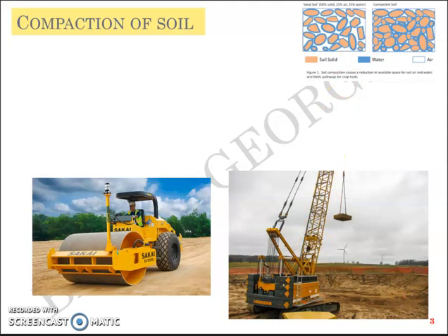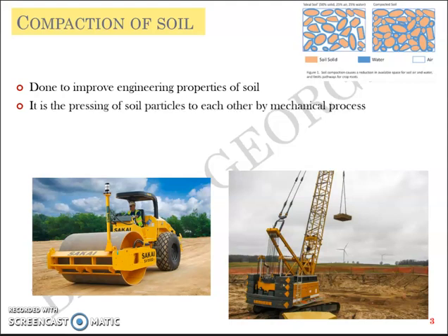So fundamentally, compaction is done to improve the engineering properties of the soil, and it's nothing but pressing of soil particles to each other by a mechanical process, and it involves expulsion of air.